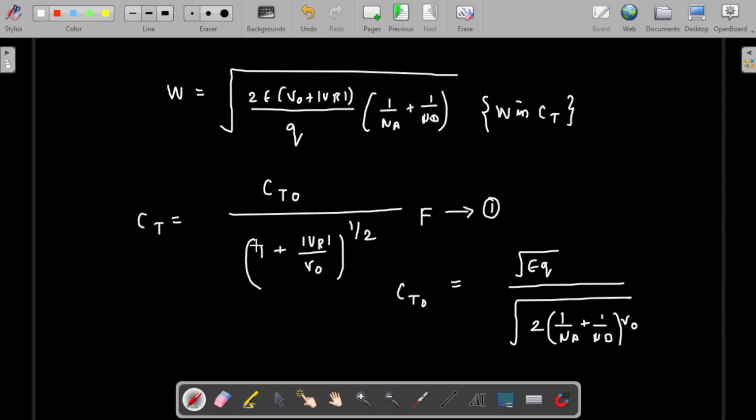So from this we can generalize the thing. So it will be 1 by 2 if it is a normal uniformly doped junction. The power will be 1 by 3 if it is a linear junction or non-uniform doping profile that I already discussed in the previous lecture. So this is because of the reverse bias.